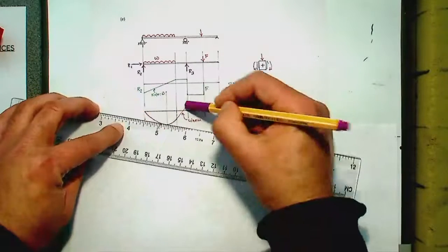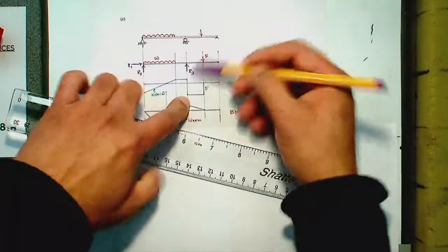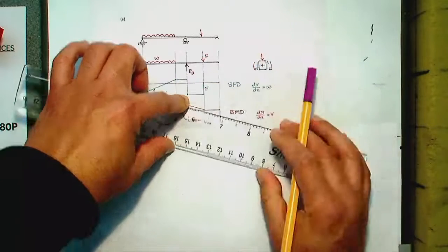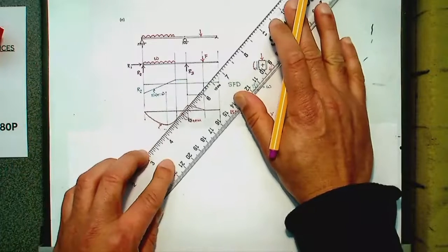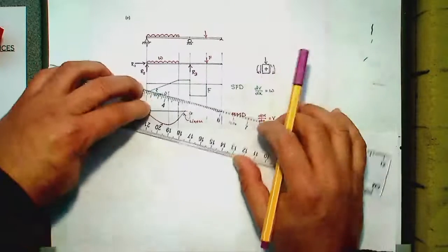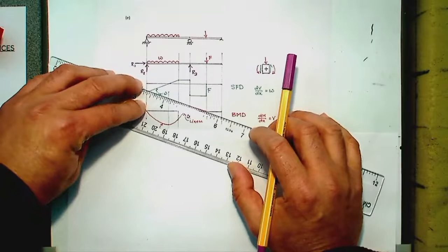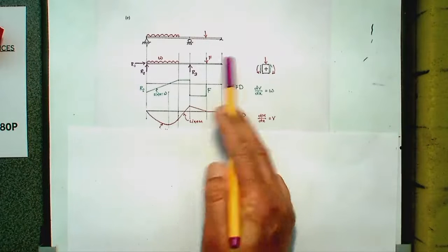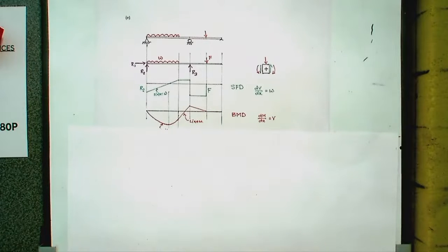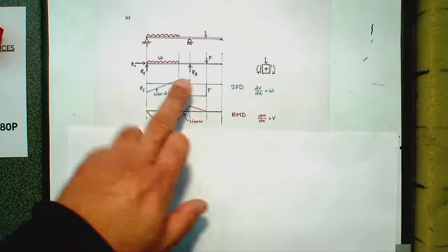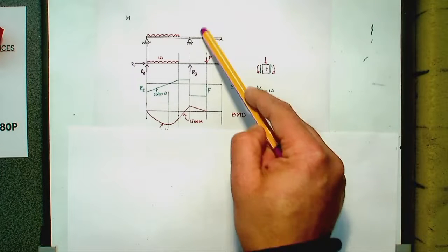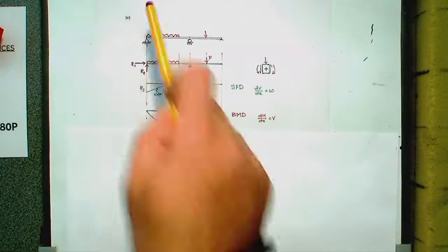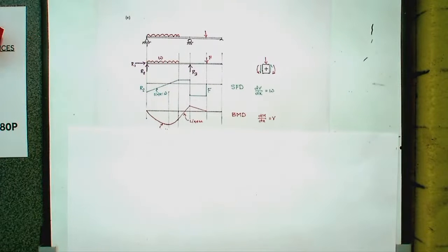So I am at this point, and then from this point, the shear force changes positive to negative, so my slope will change abruptly from positive to the negative slope. Okay? And then, of course, there is no load, nothing, and a free end, so there would be no shear force, no bending moment. Now, this is assuming the effect of this load was lower onto the left-hand support compared to the effect of the UDL.